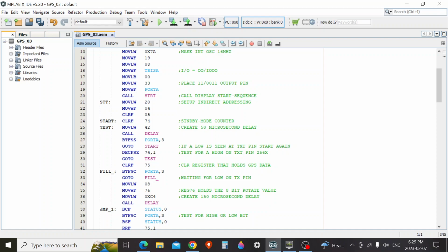In this case, I'll look at it 256 times, and it has to be high every time before I'm convinced that it's really on a high or a standby state. And at that point, when I finally feel that it's definitely at a standby state, line 32 to line 33, I start waiting for the low. That's what it's doing there, just circling around, waiting for a low to happen between line 32 and line 33.